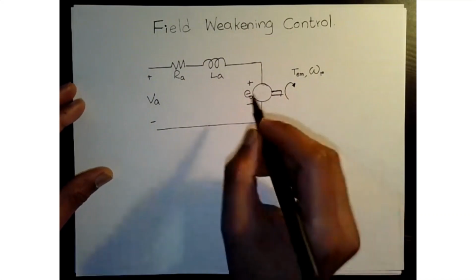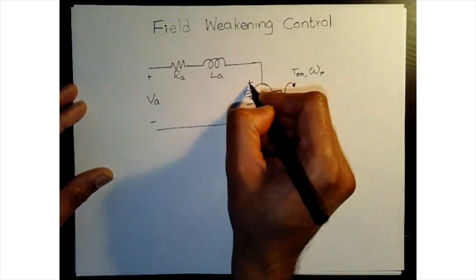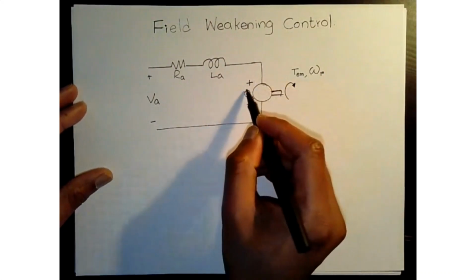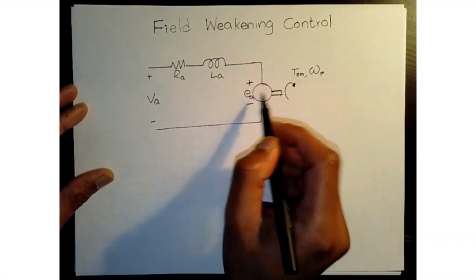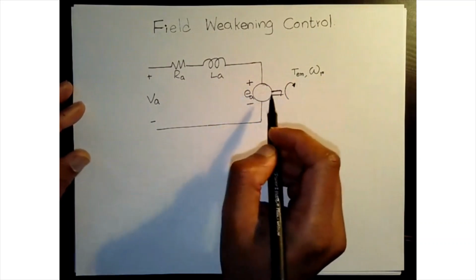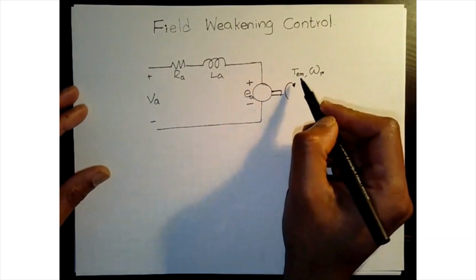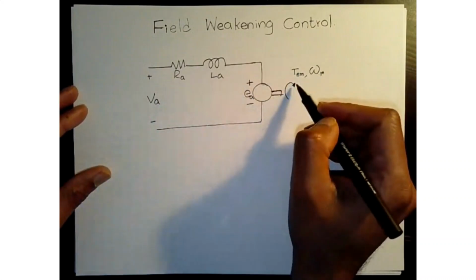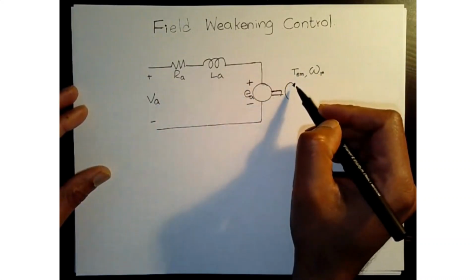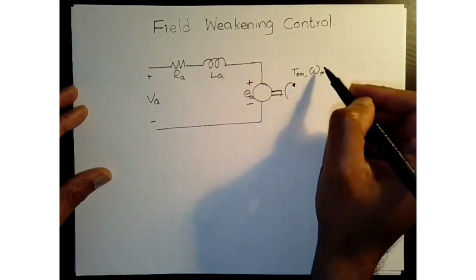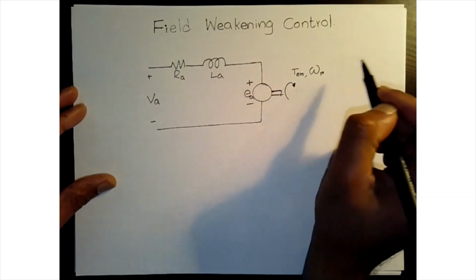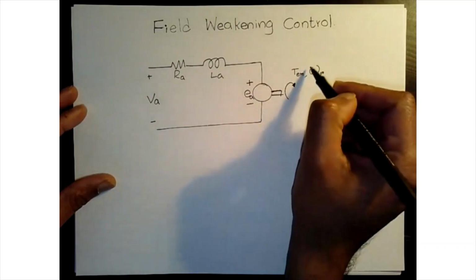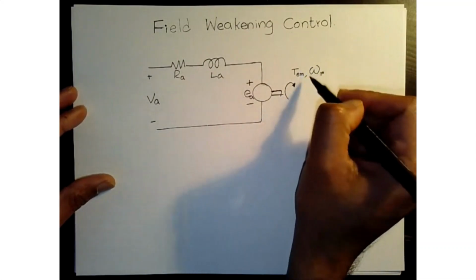Morgan, do you mean factors that influence back EMF, current and torque? Now, current and torque are indirectly influencing, because current results in electromagnetic torque, and then torque passes through the mechanical dynamics before we see a speed change, right?